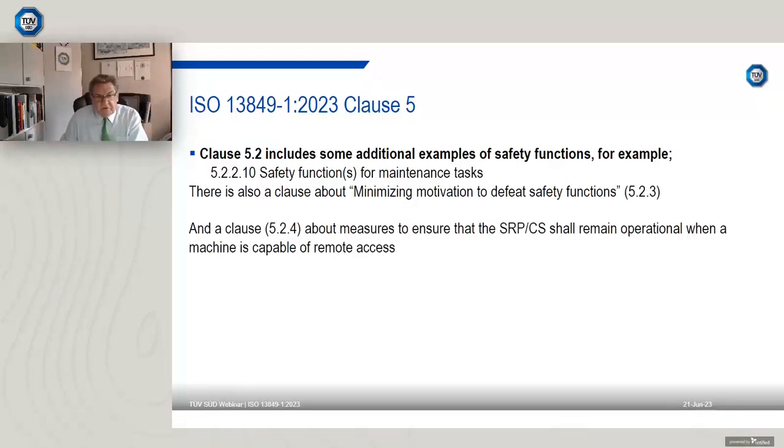There is also a clause taking account of seeing more systems that are capable of remote access, and where that is the case, then we have to ensure that the safety related parts of control systems, the SRPCS, remain operational when the machine is capable of remote access.